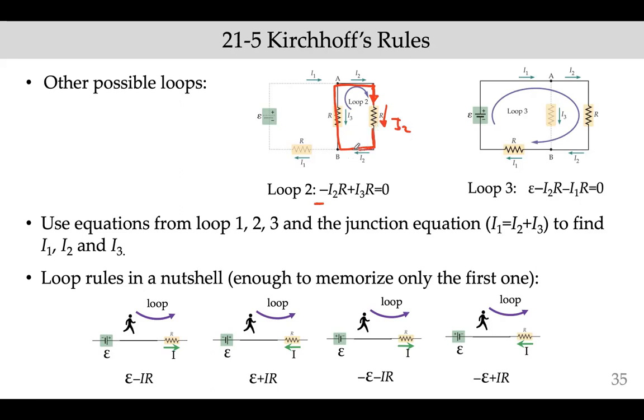And so we go in this direction. As you see, there's really nothing here, so we don't write anything. Then you run into the second resistor. And again, you ask the same question: is the loop direction, which is in the up direction, and the current, which is in the down direction here, the same? If they're the same, you put a negative sign, but because they are now opposite, you use a positive sign.